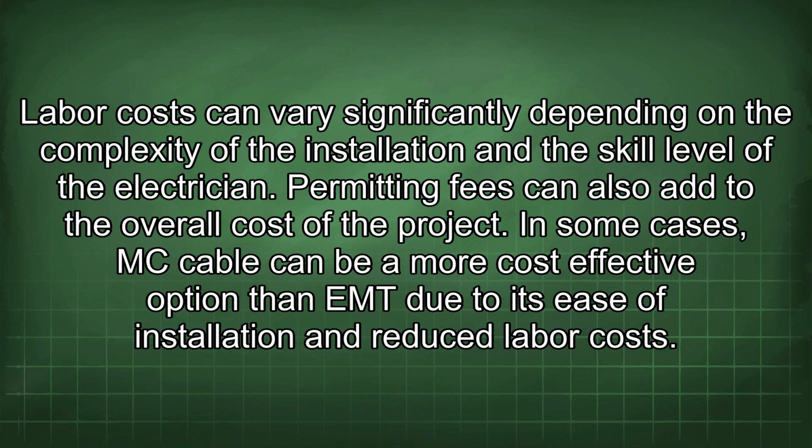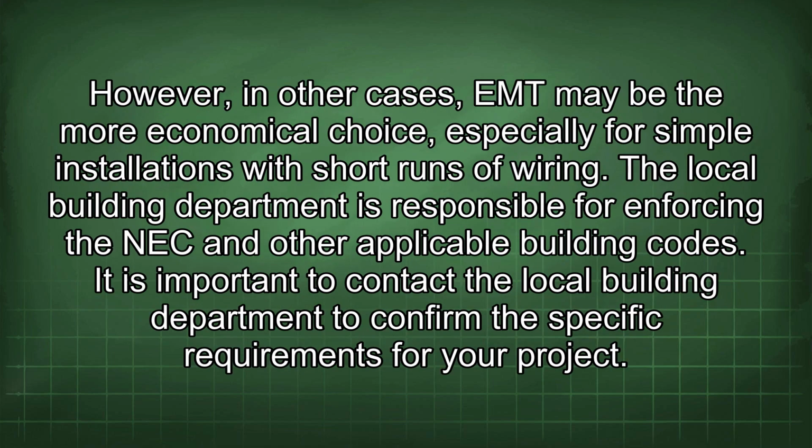In some cases, MC cable can be a more cost-effective option than EMT due to its ease of installation and reduced labor costs. However, in other cases, EMT may be the more economical choice, especially for simple installations with short runs of wiring. The local building department is responsible for enforcing the NEC and other applicable building codes.